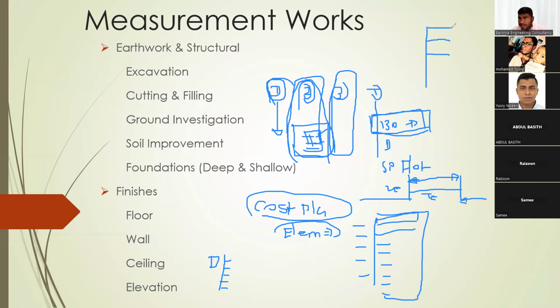I'm telling you here, first the cost planner makes the quantities, then the bill of quantities, then they float the tender, which is also a QS duty, because you study procurement. Then during the tendering phase, the contractor will ask so many questions because he might not understand an item in the bill of quantities, he might see a difference in the quantities, or he might not receive the drawings perfectly. So tendering is also part of a QS job.